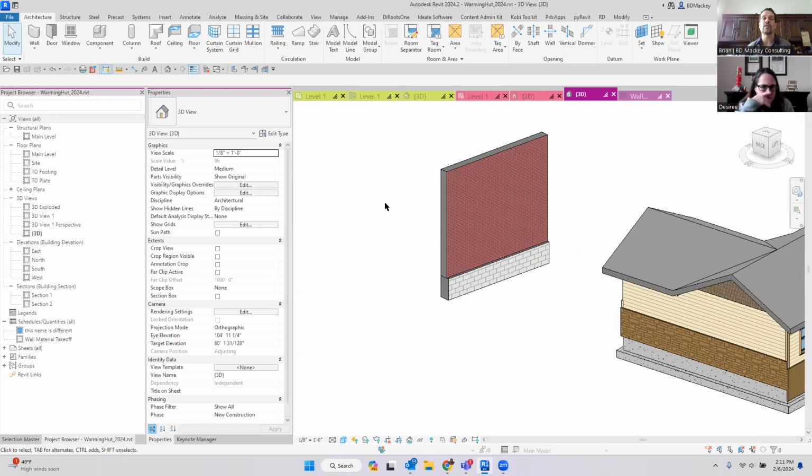No. So that's part of the things when Revit brings in things like that, you end up getting what's called a direct shape file inside that family. And that direct shape file is what it is. It's a one-time off scenario. You've just got to deal with it the way you can deal with it.